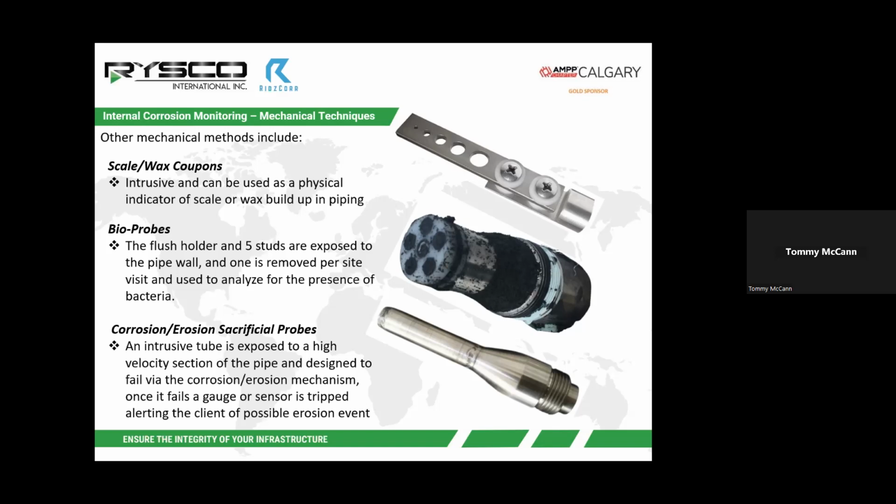When you have corrosion, or erosion, also you can have straight erosion, that tube fails, and then pressure passes through the body of the probe to a device which will alert the client that it has happened. That can be as basic as a pressure gauge, which is just manually checked by operations, or you can go all the way to a pressure differential switch, which will alarm in, for example, a controller.